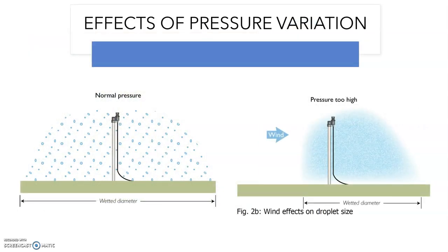In this picture we are using this in day-to-day life. We have placed these heads with the help of the riser. One more issue: if we supply too much pressure, obviously the system heads will emit mist. It doesn't give droplets; it starts to give us mist if the pressure is too high. So the throw diameter is only up to this level, but we targeted this whole area, and in this condition it just wetted this area only.